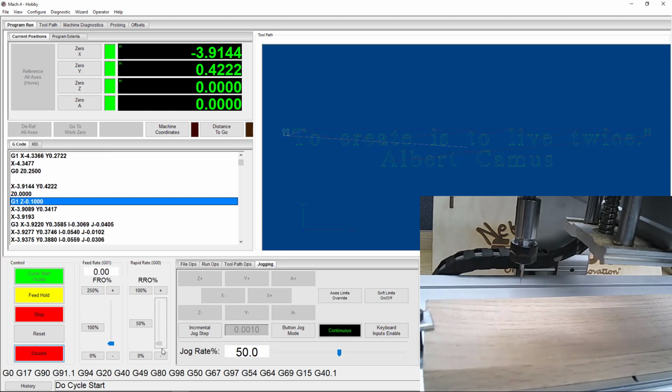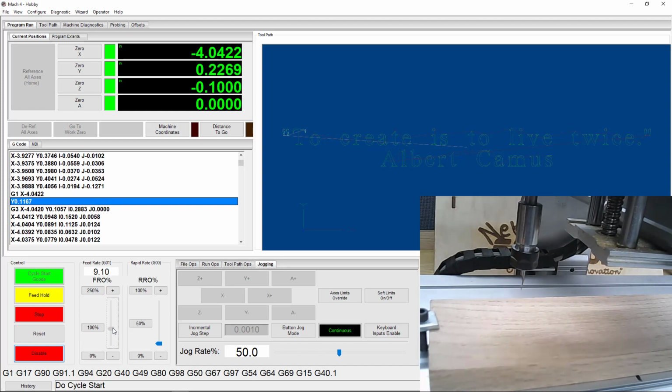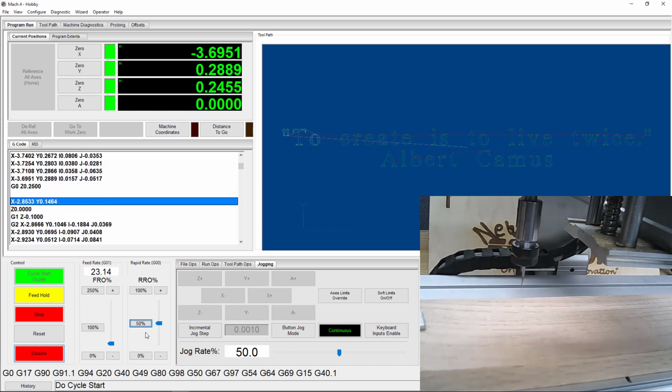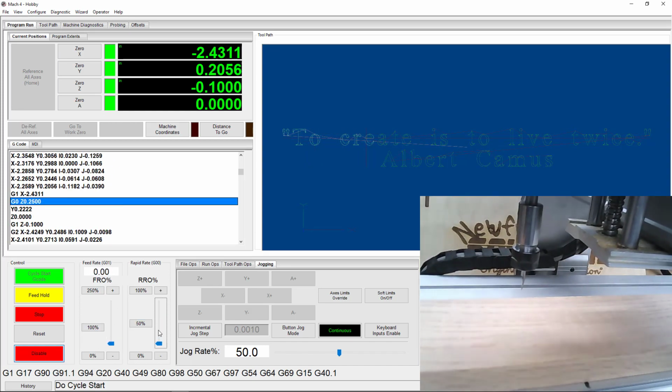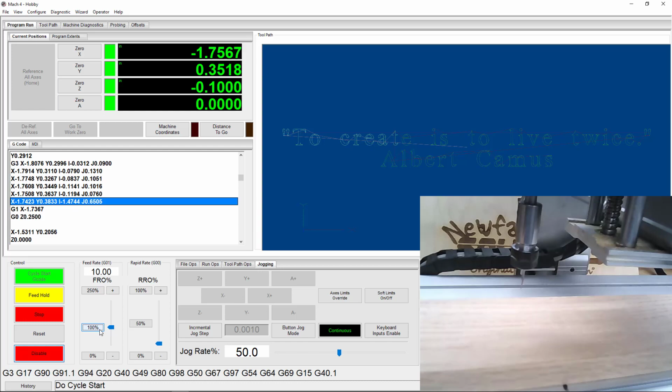While it's always important to be vigilant, there are 3 moments you want to pay special attention to. You are most likely to crash at the beginning of a cut, during a tool change, and at the end of a cut, so watch carefully during these parts of your project.